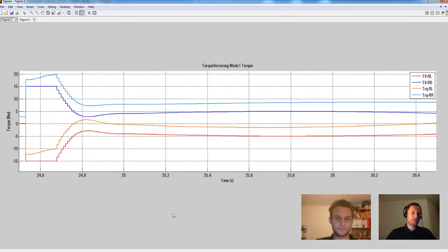Okay, got it. Then we see that the signals keep a certain level for a small time, a lot less than a second, and then decrease again in steps. Where do these steps come from? These steps are coming from the sample time of the controller. And it finally decreases because the step steer is only very high at the beginning, and finally you achieve the desired vehicle behavior value. Yeah. Okay.